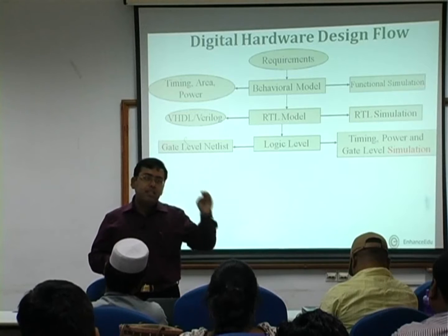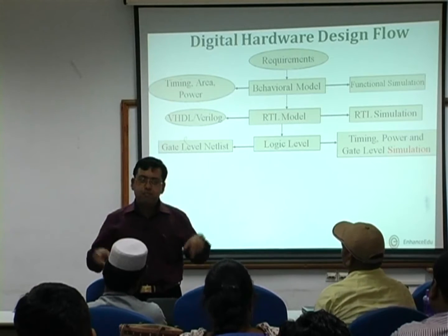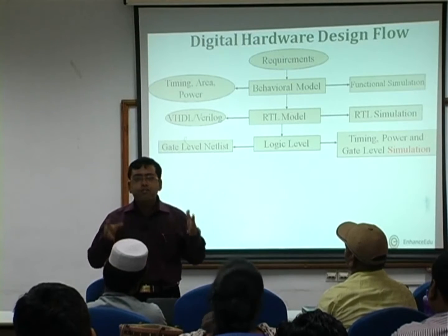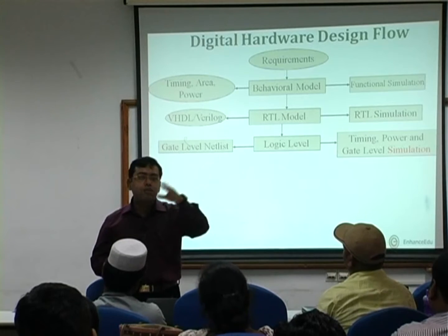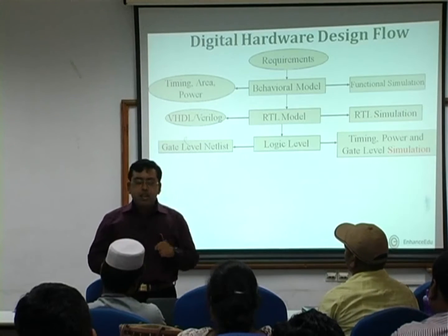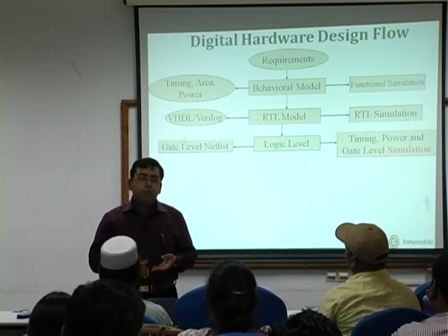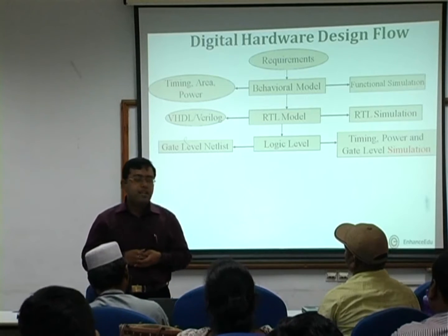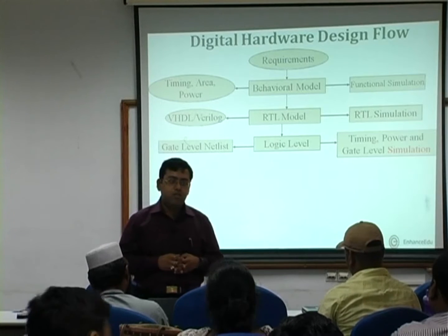We can specify the individual components of a circuit and specify the pins that are connected to it, or we can take up individual nets or wires and specify the components that are connected to it. In the former case, we call it a component oriented netlist or a module oriented netlist, and the latter case we call it a net oriented netlist.